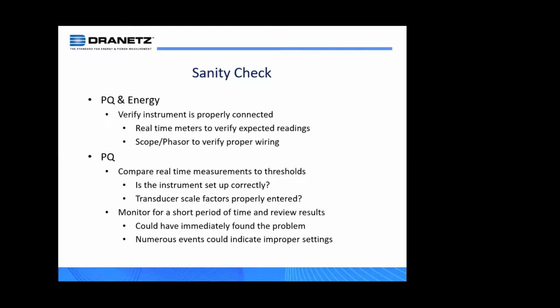Make sure when you walk away from the instrument, because if you're doing an energy survey and you want to replicate what the utility is doing, then you're probably going to leave the instrument there for at least a month. So before you walk away from that instrument, and you're not going to come back until a month later, you want to verify that all these numbers, or what I call the sanity check, are valid.